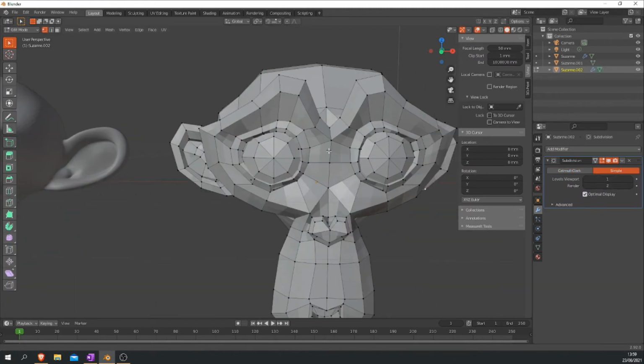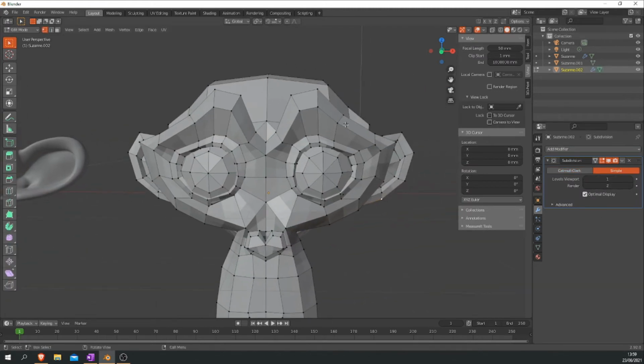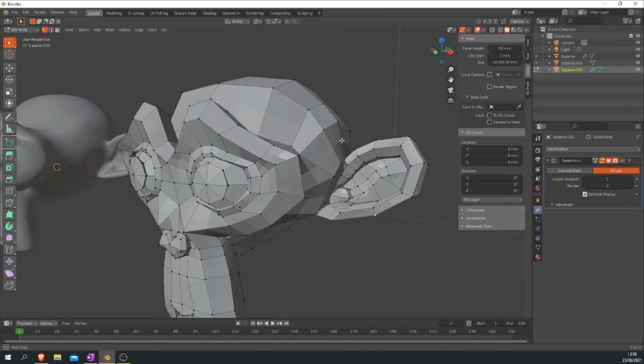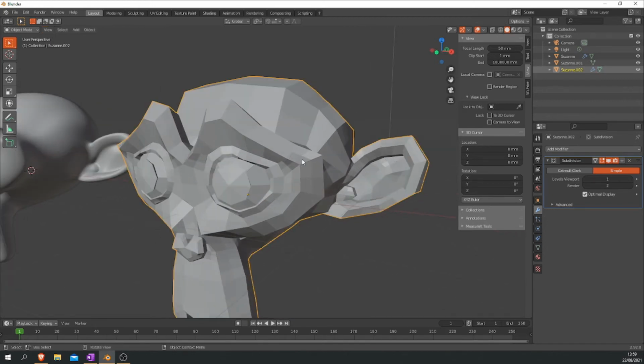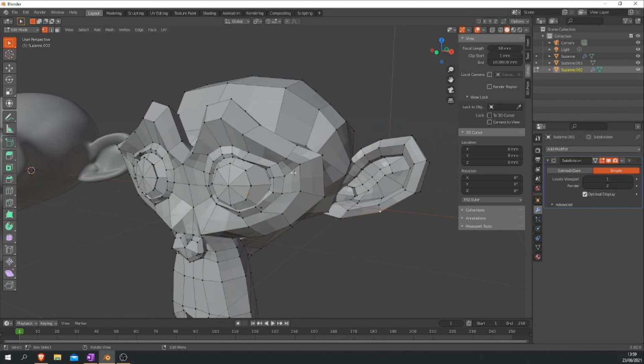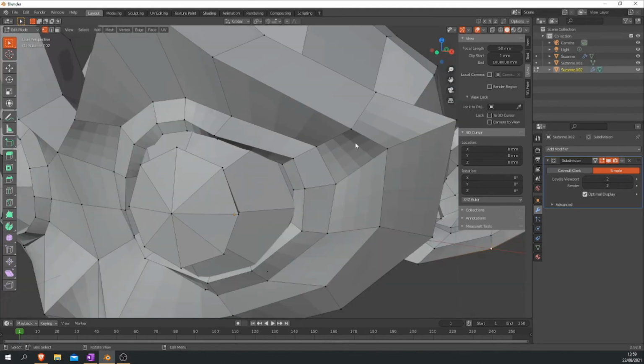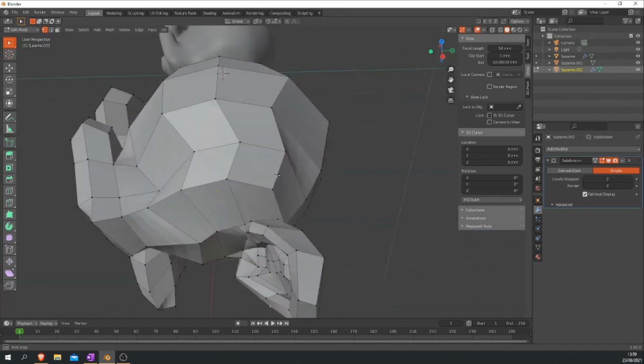Now with this one, it will literally just subdivide each surface into a new face. So this face here, you can see that there's going to be 4. This has gone up again. See if you zoom in there, we'll see it. So that's after. So 1 face, 4 faces, 16 faces, and it's done that throughout the entire model.